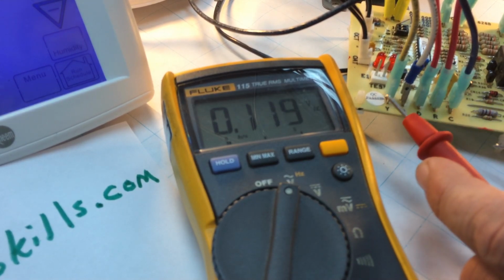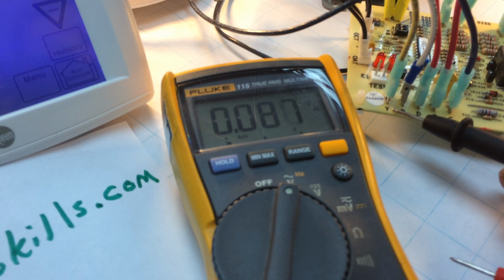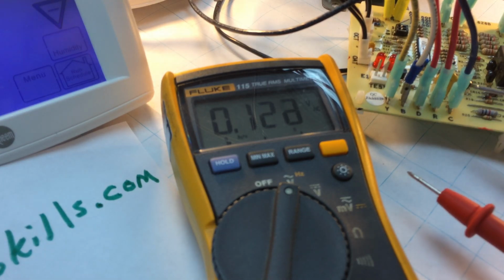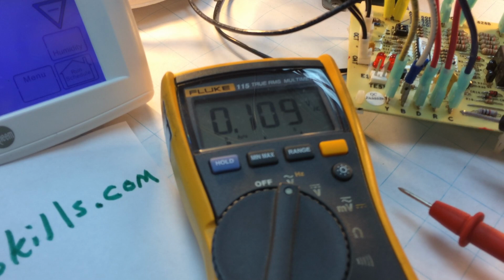This defrost control gets the Y signal from the thermostat, and if our time delay has expired, our pressure switches are closed, and there's no other faults within the control, then that board will allow the signal to continue on to the compressor contactor coil, and that's what gives us our compressor and outdoor fan operation.